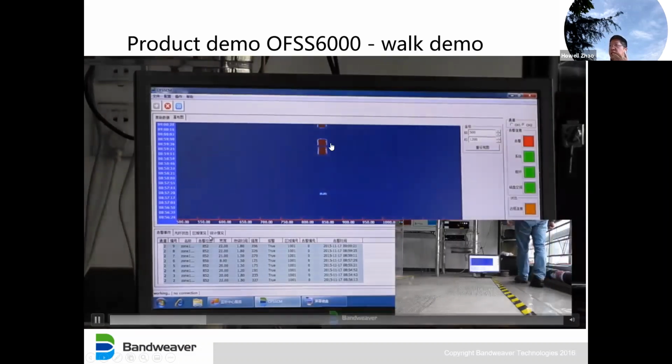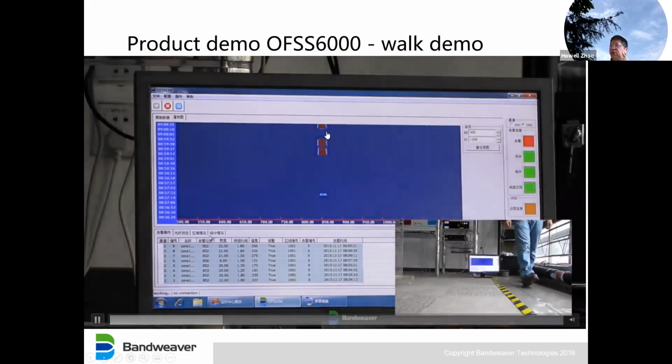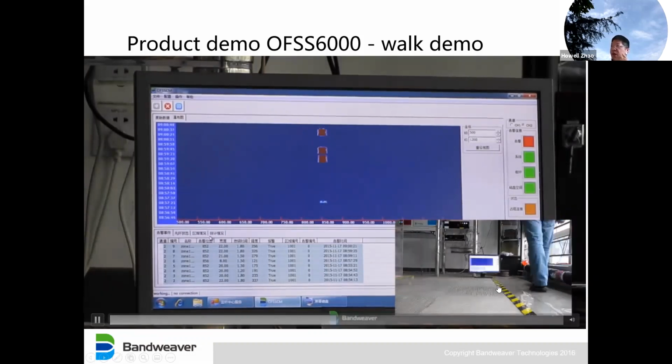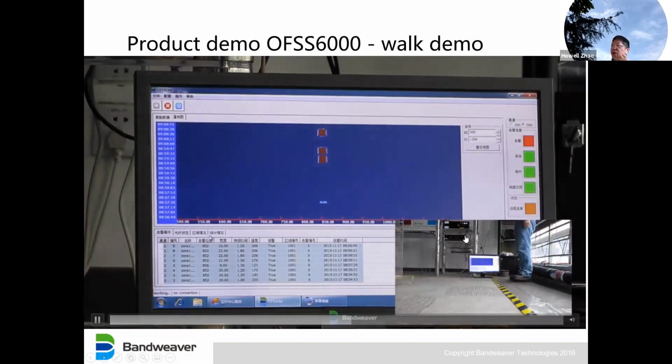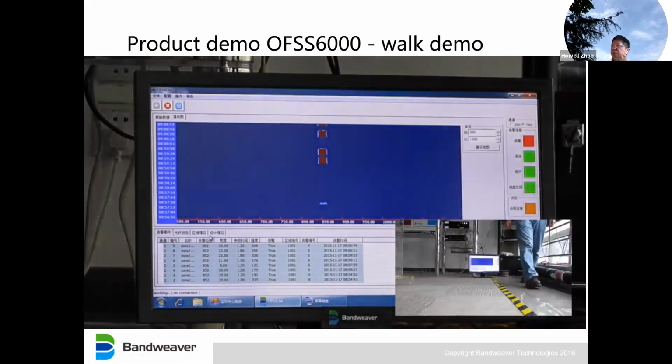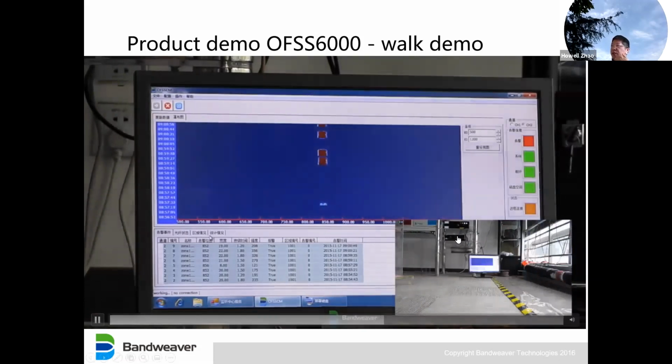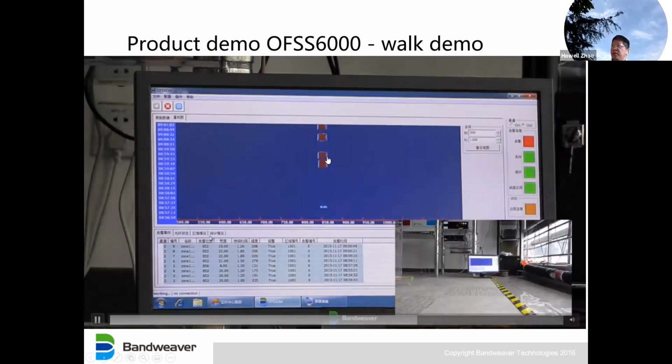So walking can give the signal on the display. It's a walking. The fiber is under the label here. Then you see the walking, the steps make the vibration. The vibration is transmitted to the fiber. The fiber can detect, and the backscattering signal will be recovered by the electronics and the software. So finally, we get the data displayed here to understand the steps.